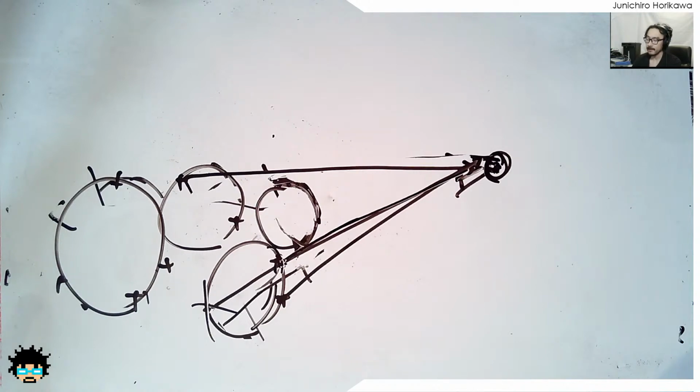Right. Now it's time to calculate the intersections. Like I did before, I'm going to first create output parameters for the intersection point and the UV, and calculate the intersection using intersect 0 at P plus.